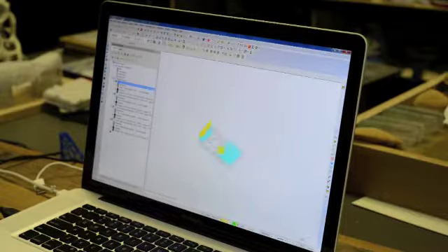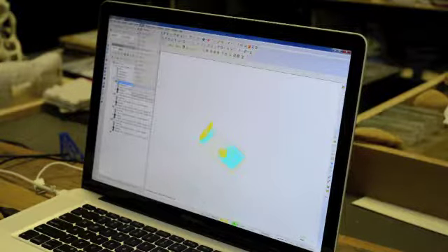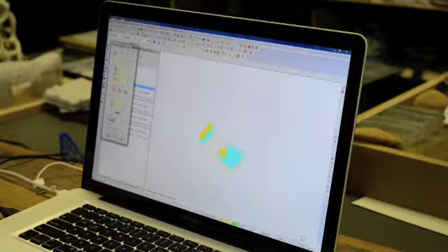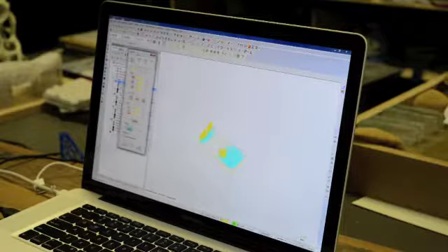And then the other thing that's kind of nice, if you have a big piece of stock and you've got a bunch of parts laid out on it and you really just needed to move things a little bit, you can just select everything, go up to X form, translate, and it's going to pull up this box, and it's going to be defaulted with this radio button that says copy.